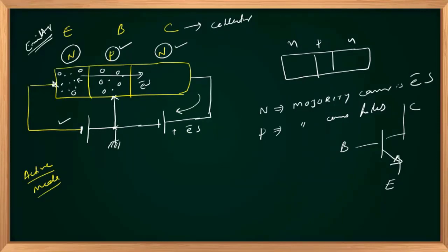So emitter region emits the electrons in this example, and the collector region collects all the emitted electrons coming to the collector region. So here electrons are emitted, electrons are moving towards right, implies this negative pole should supply enough number of electrons so that these electrons will replace the electrons migrated towards the collector region. Right? So electrons are actually flowing into the emitter terminal. So the conventional current is just opposite to the flow of electrons. So emitter current IE is flowing out of the emitter terminal.